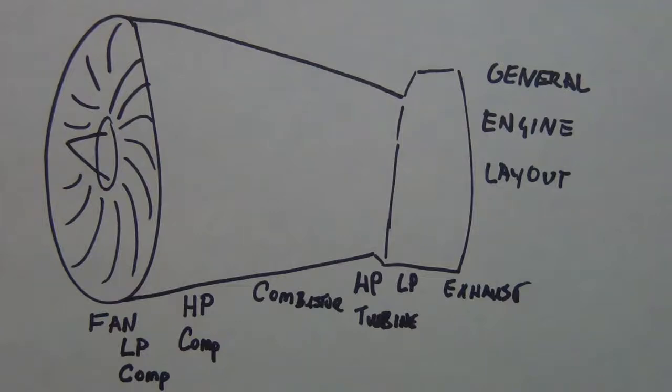After that first stage, it goes to a high pressure compressor stage. I say stage meaning a section, because when we talk about the definition of stages, we're talking about the number of rotors and stators, the way they're designed. It depends on which model or variant as to how many stages. In this particular case, there's 9. It could be 7 or 9 stages depending on whether it's a dash 5A or B or some other variant. So just keep that in mind.